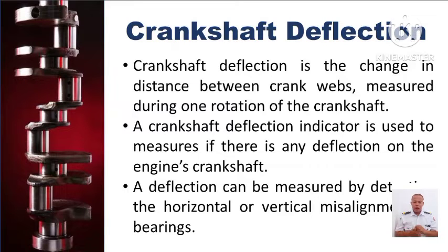So this crankshaft deflection is the change of distance in our crank webs due to some faults in the system, like low oil pressure, abnormal wear of bearings, loss of bolt foundation, or even human error. Maybe they misread the last time, so the situation got worse. If this crankshaft deflection becomes worse, it will lead to breakage of the crankshaft, and the other parts connected to it may possibly be damaged also.